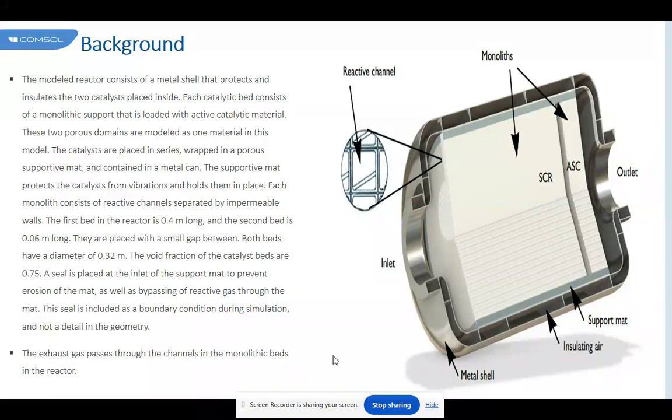In the fourth analysis of transient behavior and temperature front propagation, the next one is the analysis of the effect of the substrate on cold start time. We analyze the transient behavior of the monolith and the dependence of the cold start or cumulative emissions on the substrate properties. In this next and last section, we present numerical simulations that are guided by the analysis.